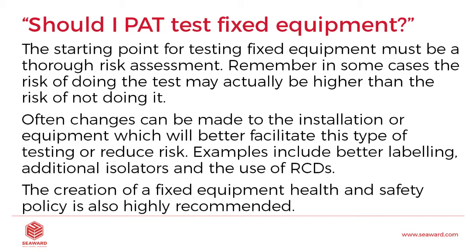So often many things can be changed or altered to the installation or equipment which will better facilitate this type of testing or reduce the risk. For example, you can include better labelling on the distribution board, you can add in additional isolators, and maybe obviously the use of extra RCDs.